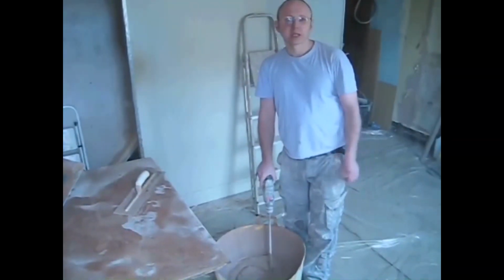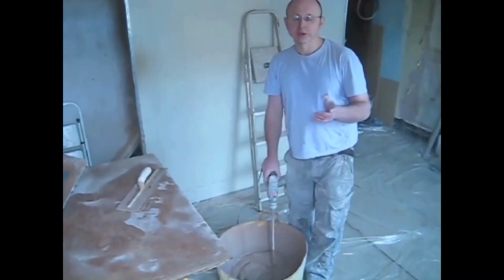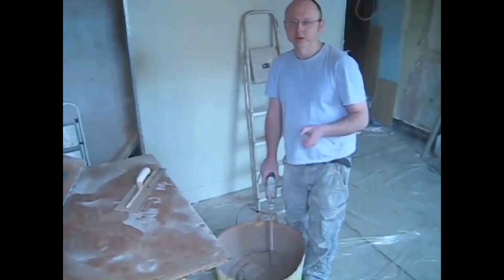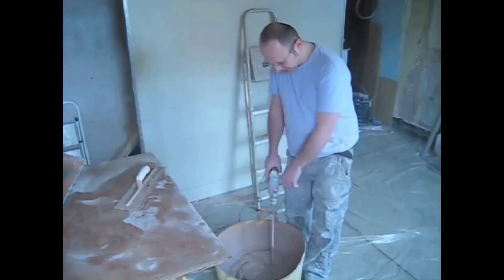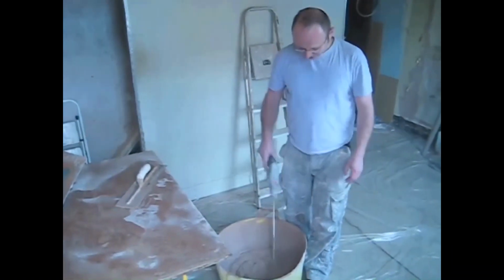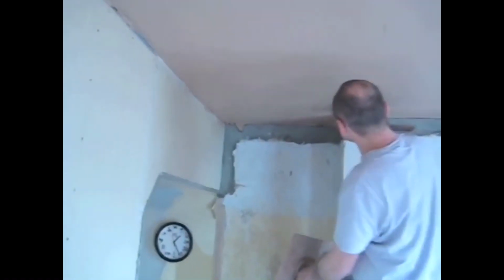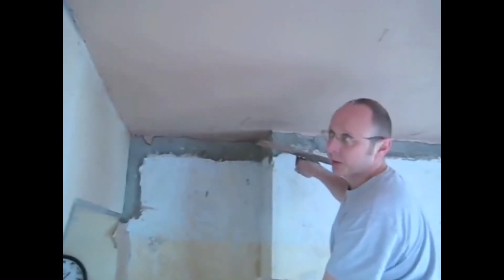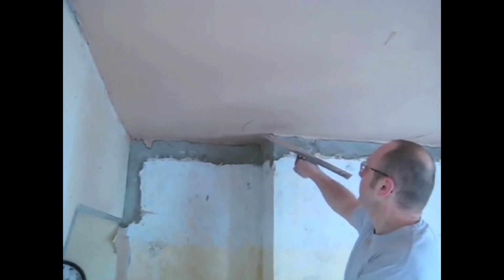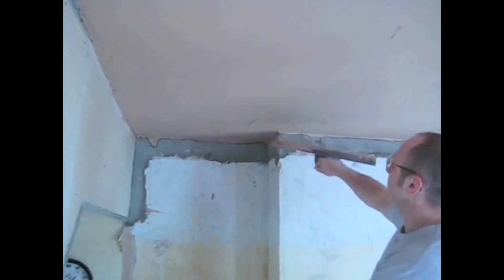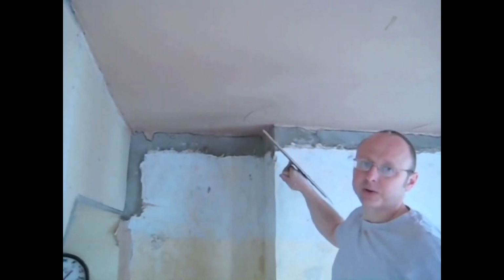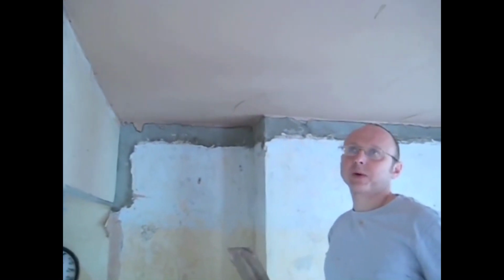Now, as we're doing the ceiling, it wants to be quite stiff, not too wet. We're doing walls wetter, the ceiling's a little bit stiffer, so that's probably about right. And especially when you get to places like that, if that was the first coat, you'd really want to be levelling that out because the second coat is really difficult. The second coat should be really thin. Okay. See what I mean? But it's really good when you go.